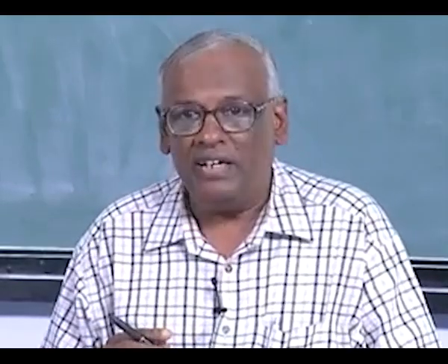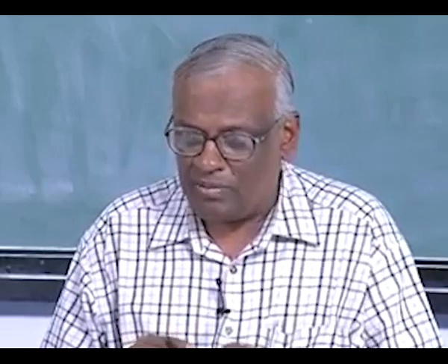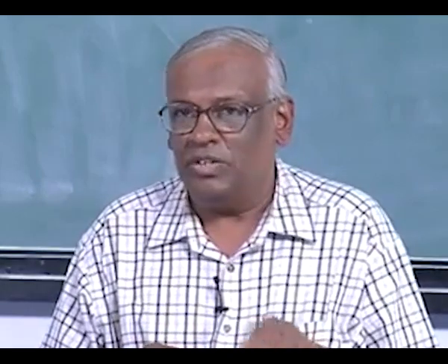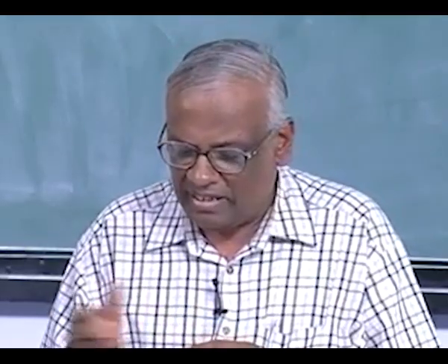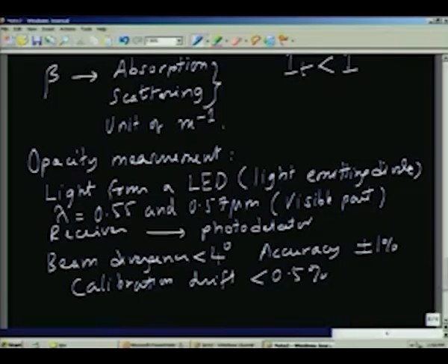One can use that. In laboratory practice, we might use a helium neon laser instead of light from an LED. In the case of light from an LED, you require a lot of optical elements, because you need a lens, a focusing arrangement, and so on, so that you get less than 4-degree divergence, and then of course, you have to collect the signal at the photo detector by using suitable optics.